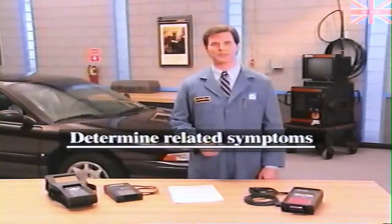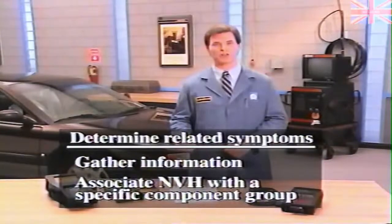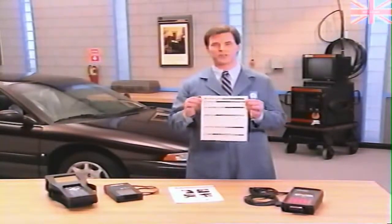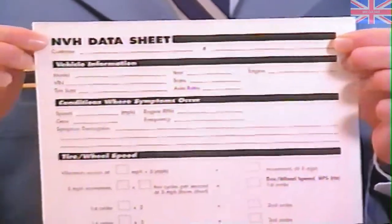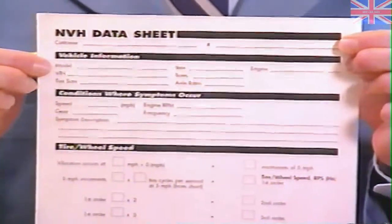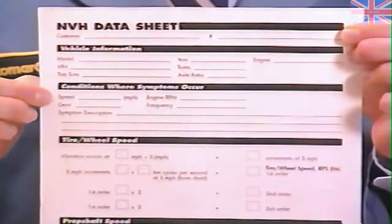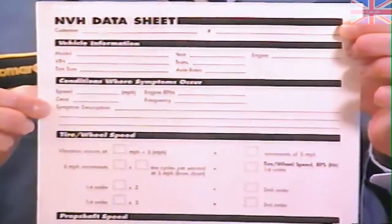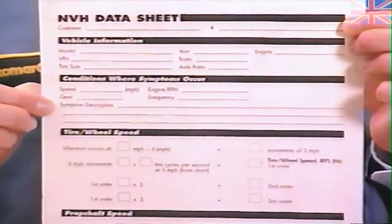Determining related symptoms involves gathering as much information as possible and associating the noise, vibration, or harshness with a specific vehicle component group. When gathering information, use a worksheet like this one found in your reference book to record important information like make and model, year, engine size, etc. When the symptom occurs, note the corresponding speed, RPM, and gear. Record a detailed description of the symptom or symptoms and identify the frequency range of the noise or vibration.